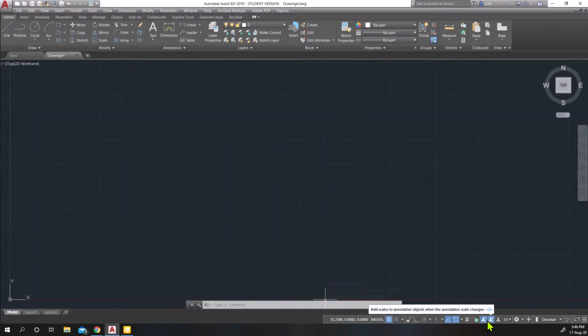And then on the very, very bottom, we have our status bar. So our status bar helps us figure out what the status of some of the commands are, or some of the settings. I have coordinates, I've got model or paper space, very important to know. I've got some grids and snaps, whether I'm drawing straight or on angles. I've got an annotation monitor, so this tells me if I'm annotating at certain scales. And also units, right? What unit am I working in?